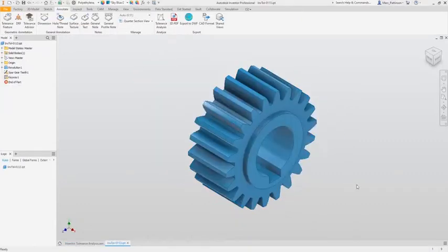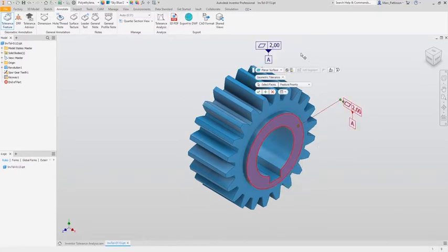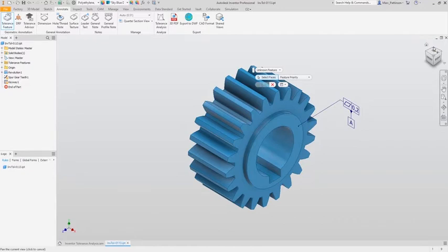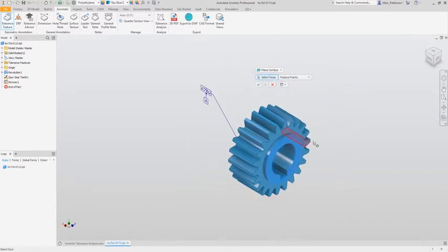We're now going to take a look at our gear component. By specifying a tolerance feature found in the geometric annotation panel, we can specify our tolerance of each face on our gear. Adding a value of 0.2, doing the reverse side, we'll find that now when we're adding this, that both tolerances are linked together.